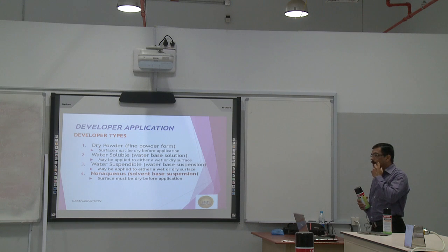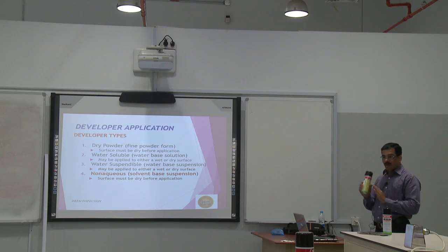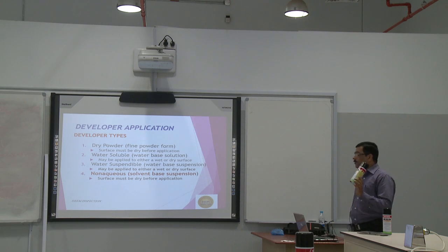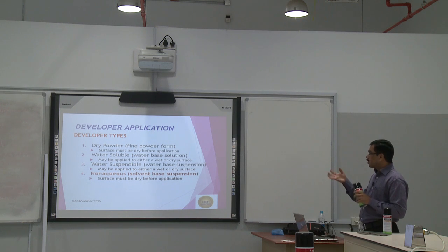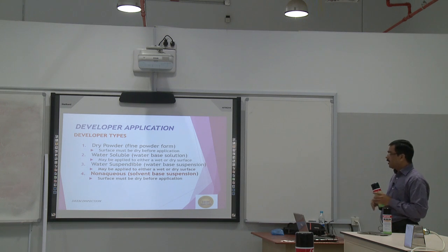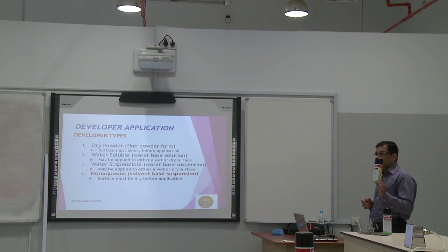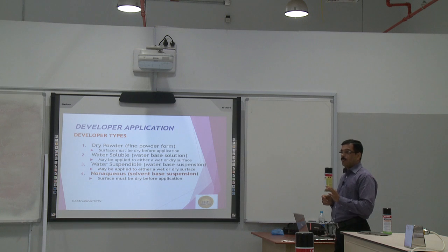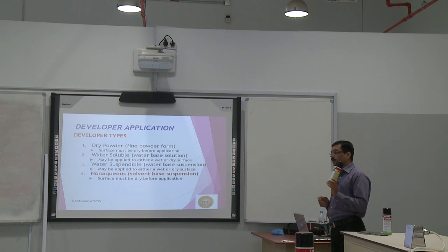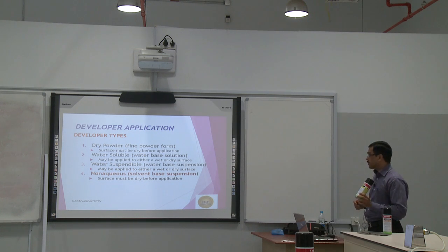Like different types of penetrant, we have different types of developer also. In this case, we are using non-aqueous. Non-aqueous means it is solvent mixed. There is also dry powder, some water soluble, some water suspendable, and non-aqueous. Whatever we are using is solvent based developer, or non-aqueous developer, for our purpose.